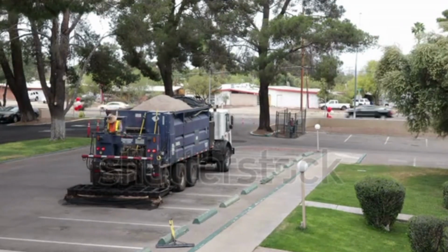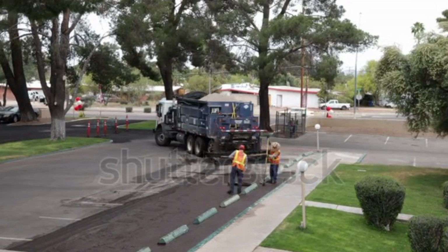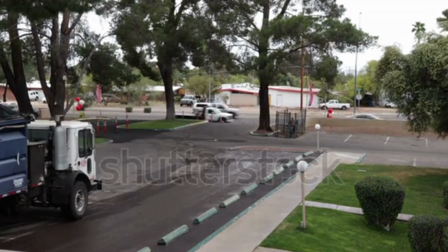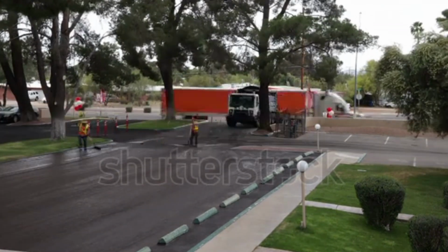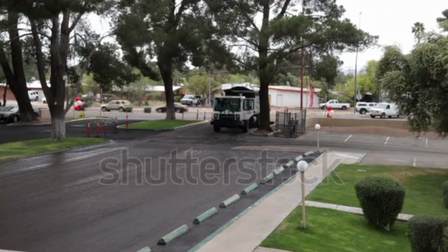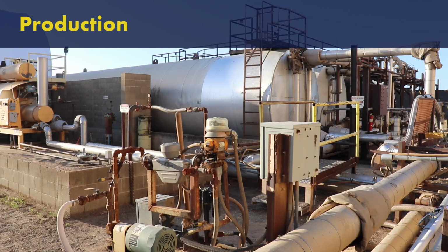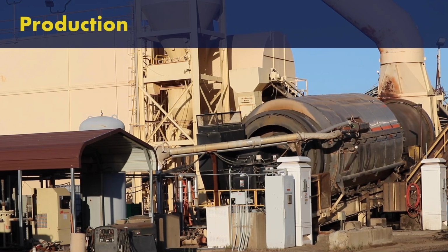Terminal blend rubberized asphalt is made at the refinery, where a finely graded rubber crumb is fully digested into the liquid asphalt and shipped to the hot plant. Terminal blends are used in dense graded mixes. These mixes are recommended on parking lots and where parallel parking is prevalent. Production methods for the high viscosity asphalt rubber binders are essentially the same for both hot mix and spray applications. For spray applications, the crumb rubber and liquid asphalt are blended in the distributor truck.